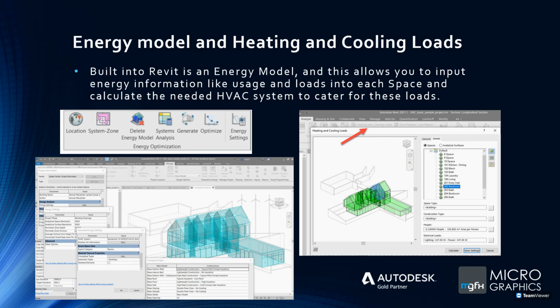And that you would then use to add your diffusers in and create a system to cater for these loads. Right, so it's a bottom-up design where each room has its own loads, and then you count them all up to define your air handling units, the particular flow and liters per second that they need to produce.